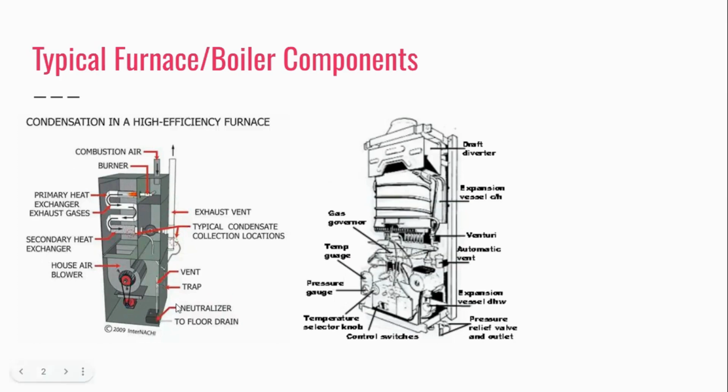That's important when you are checking things over and doing a maintenance, or if you're trying to troubleshoot something, because a lot of the time the secondary heat exchanger just gets missed and it gets nasty or it gets cracked and we don't check it because we don't know it's there. So that's super important for me to show you guys that exists.